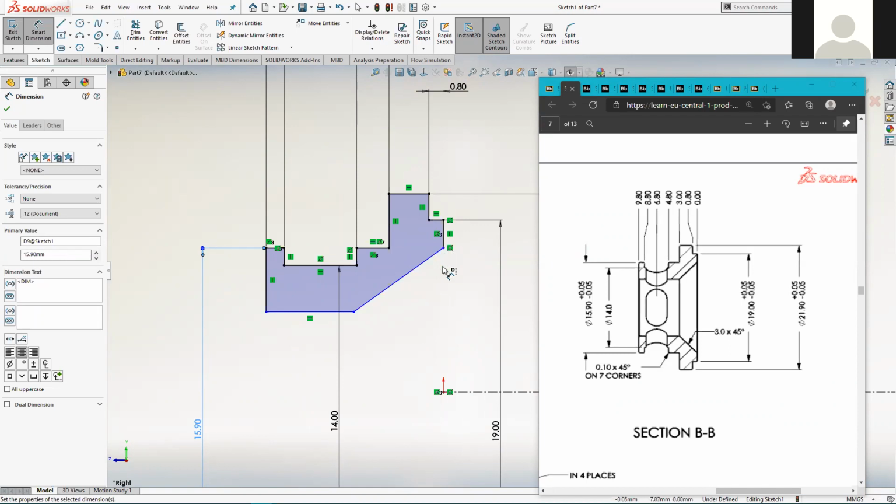And what we're going to do is run our part down here vertically and out here horizontally so it meets. And then we'll add that in as a chamfer feature in the feature manager. Which again, it's a different way of doing it, but it allows you to manage these sorts of features a lot easier rather than trying to bake them in the actual sketching process itself.